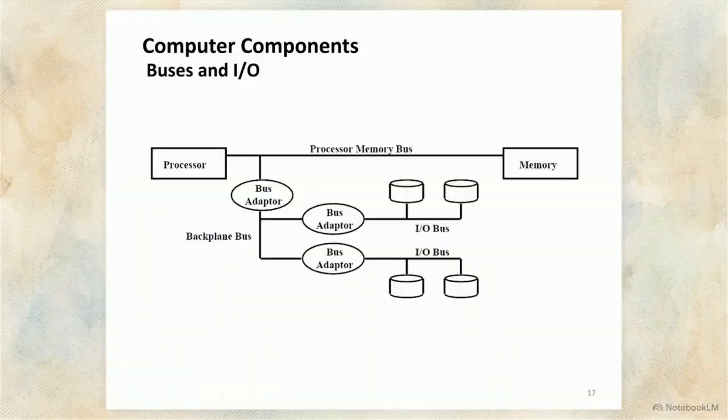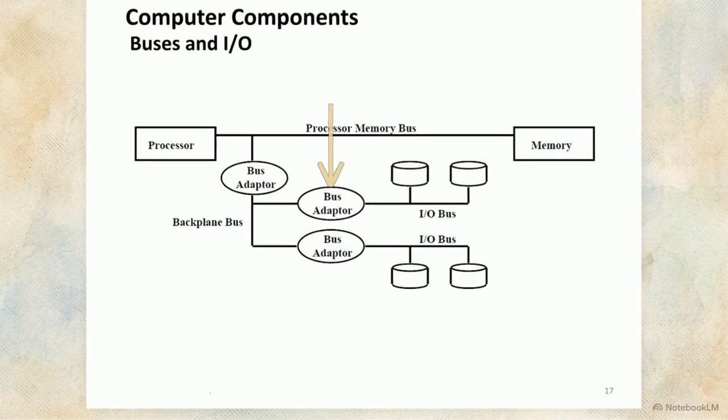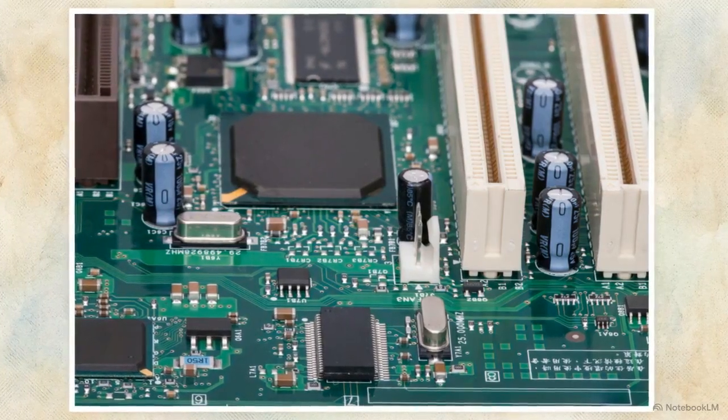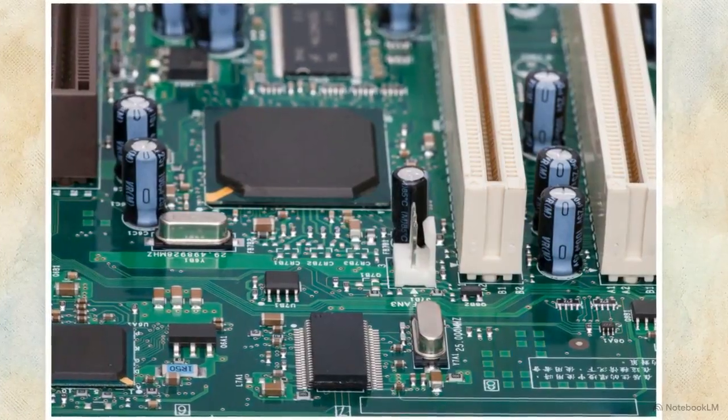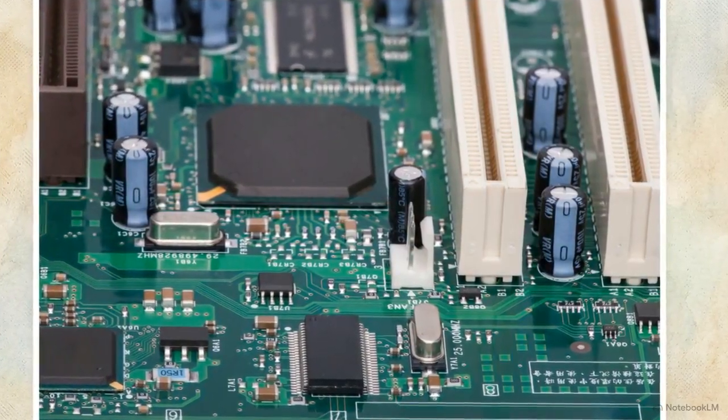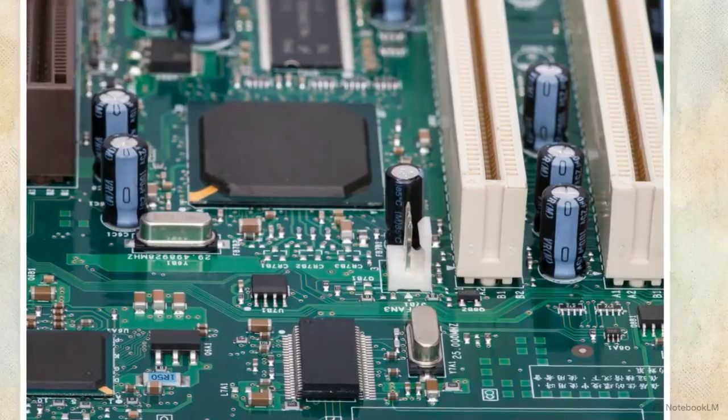The solution is a tiered bus hierarchy. The top processor memory bus is a short, extremely fast connection dedicated to CPU and memory traffic. It evolves rapidly, abandoning backward compatibility. Lower-tier input-output buses branch via adapters to handle slower, diverse peripheral devices. These I/O buses evolve much more slowly because their primary constraint is maintaining backward compatibility with legacy hardware, like older peripheral component interconnect (PCI) expansion cards.